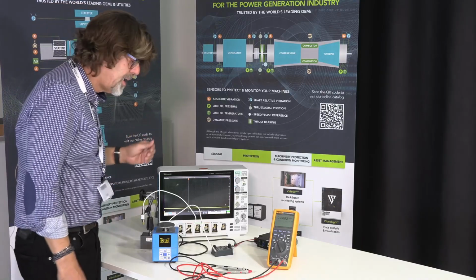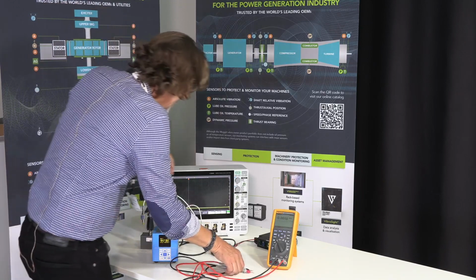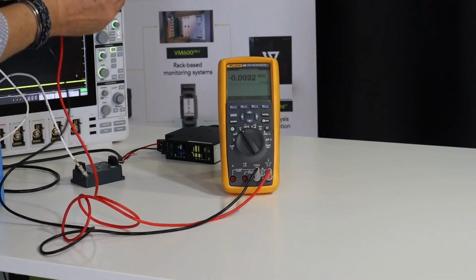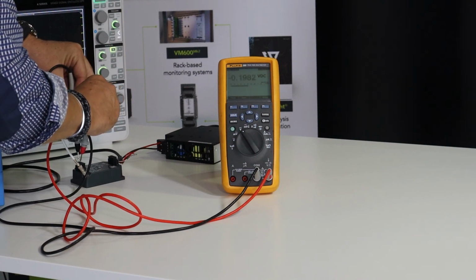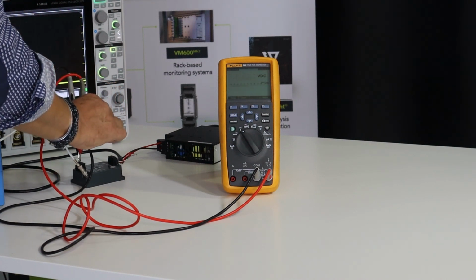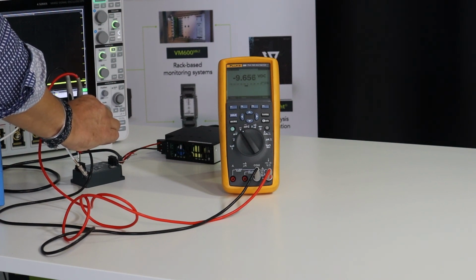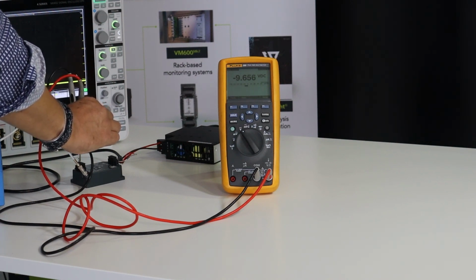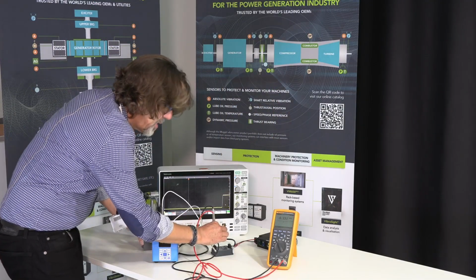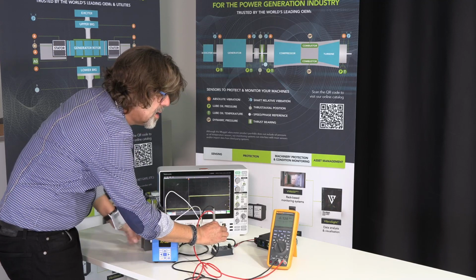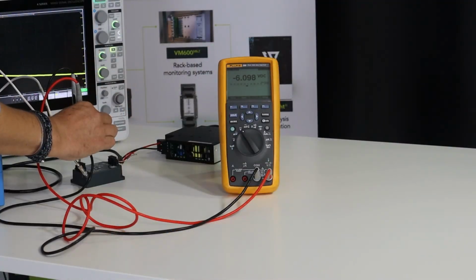So the IQS 910, like the other IQS, has the raw output. Here, with a multimeter, we can measure the voltage at the raw output. So here we can measure minus 9 volts, and if we have a vibrating target, we can see the raw value going up to minus 6 volts.